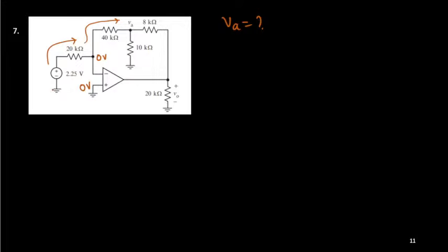Means again the same negative feedback concept that we have got. But earlier it was connected exactly to the output terminal, so this end was connected to the output terminal of this op-amp. But right now it is not at this end, but connected to the other terminal. It is fine. Whatever current is coming here, the same is flowing through this side. So this potential will be similar to earlier, minus RF by R1.